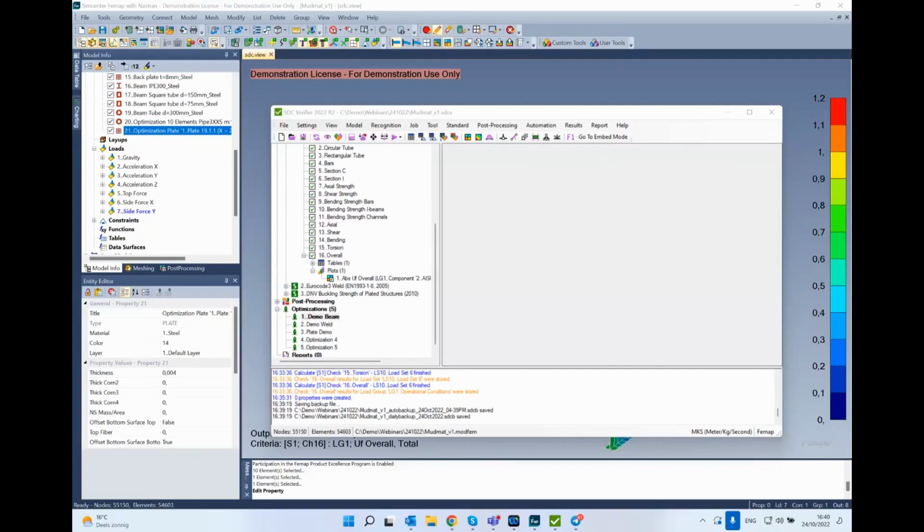Okay, I got it. Yes, SDC Verifier connects to ANSYS, FEMAP, and SimCenter in different ways. In ANSYS, we have Workbench. The idea for all three programs is the same. I have no idea how it's done within the programming part of it, but our developers managed to run it for all three programs, and it is available for SimCenter as well. Okay. And you got the workflow correct. Yes, we are not updating, we are calculating on the original model. We are just mapping the thicknesses or shapes, and afterwards you have to update.